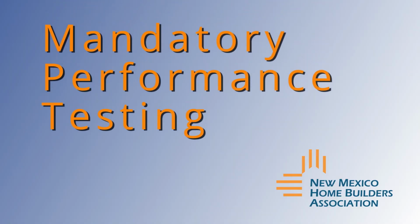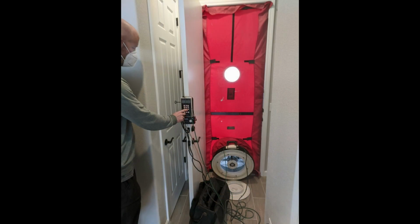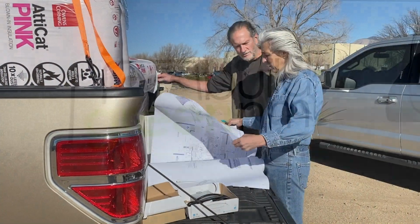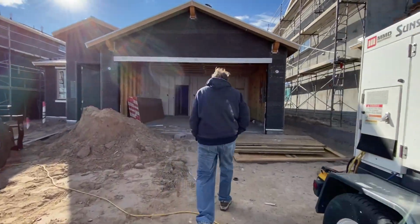The state has added a new section that requires the air changes per hour to be tested by a blower door test in certain counties. The rest of the state may continue utilizing the New Mexico Air Sealing Visual Inspection Checklist. Many energy raters have said following the visual checklist will ensure meeting the 4 ACH requirement if executed carefully. It should be noted again that those building to Build Green New Mexico or LEED H programs may trade off the ACH requirements if the home has increased energy efficiency elsewhere.